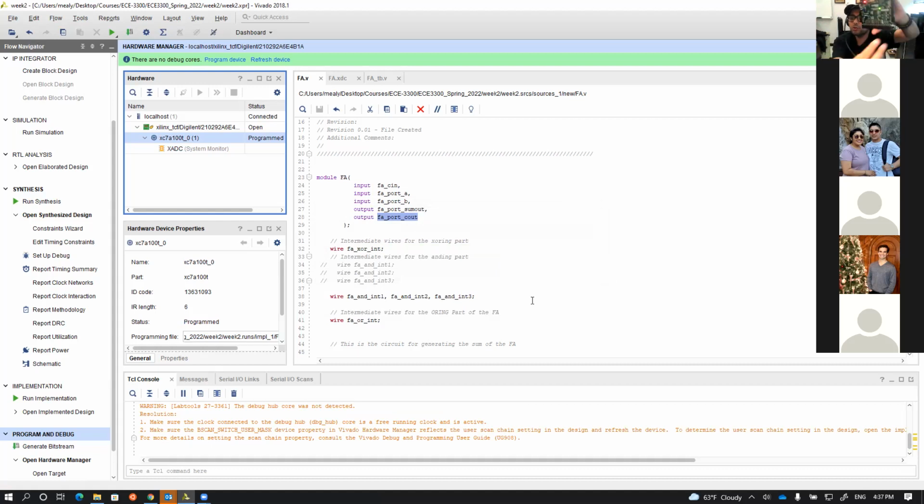So the switches, if you remember, one gives us LED 1, right? Then the other one is not active. That means the carry out came and there is no sum. Then after that it will be active. So what happened when the 3 of them went up? The carry out and the sum, both of them are what?